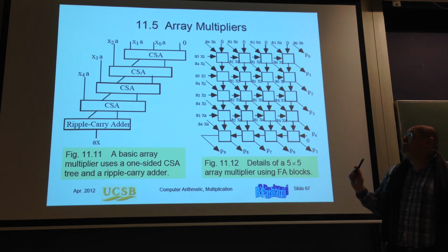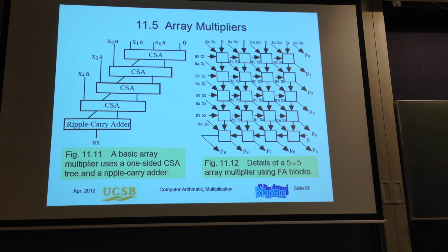And even though it's slow, because the critical path is going downhill here and then on this adder, which is downhill on this diagonal and then on this adder. It's not fast. It's regular, connections are short, and I can pipeline it. We'll talk about that next week, Monday.